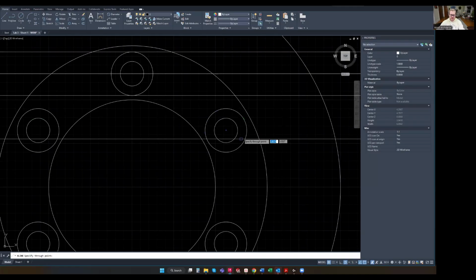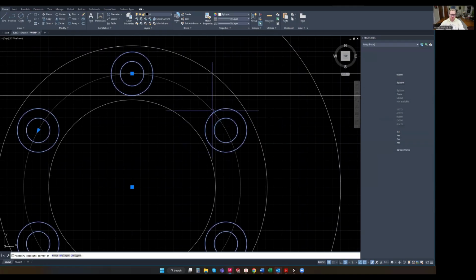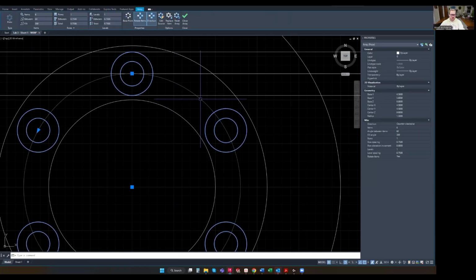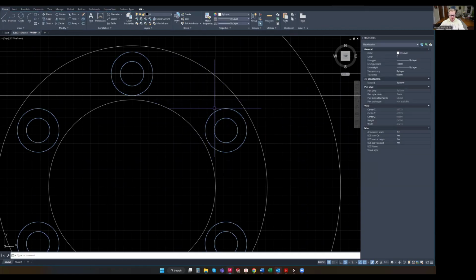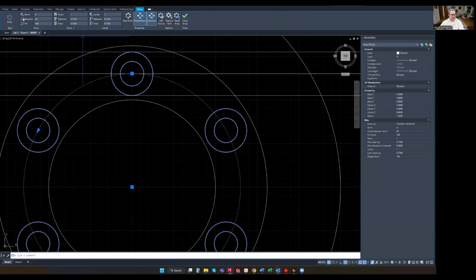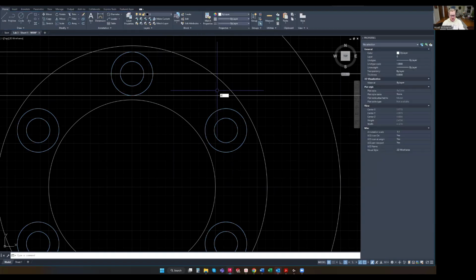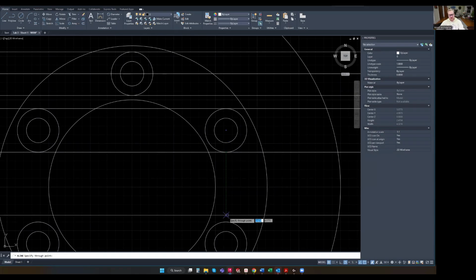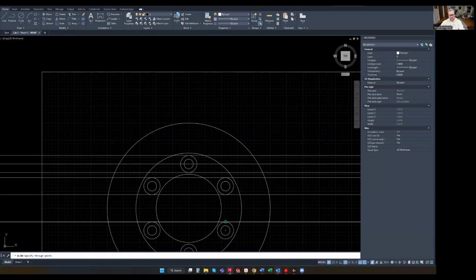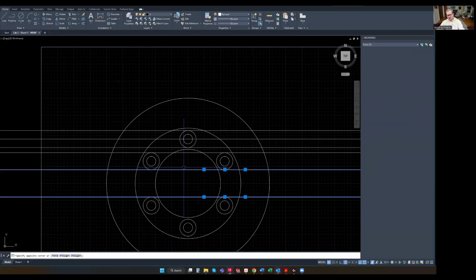So that is what we want to avoid, because later on we're going to be making construction lines. And actually, that's more like 60 degrees. It actually is 60 degrees. If you look at your array, there's 60 degrees between these. So I misspoke. Anyway, so we're going to just highlight your array. To change it back, you just highlight your array, uncheck rotate items, close array. And now when we grab our construction line, now you can then snap to the quadrant on all 6. But we're going to wait on that for now.